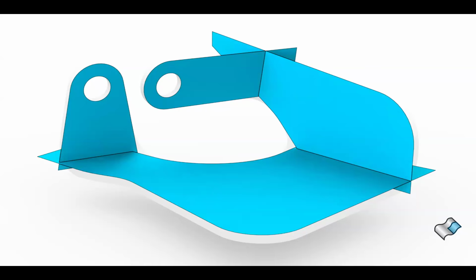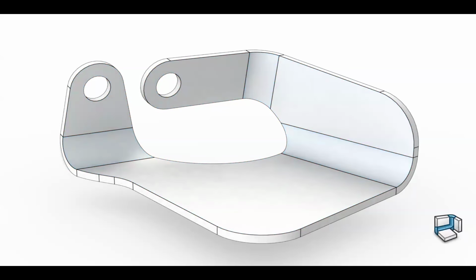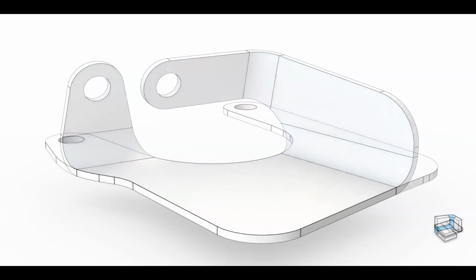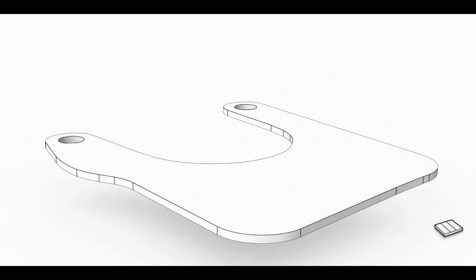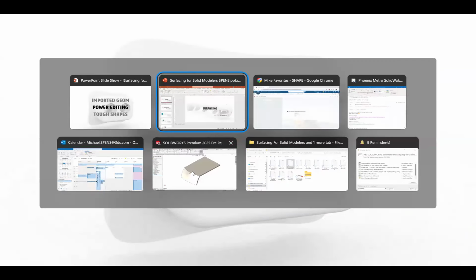So this is an example of extending them, or there's even an untrim option that will maintain the continuity of the surface when you expand it. And put some fillets on there, thicken it out, because before it's just a 0 thickness surface. And now you can use insert bends and you're in good shape. So, okay, it takes a few more steps, but if you need to do it, these are the kinds of tools that can be really helpful. So let me jump through a couple examples there first.